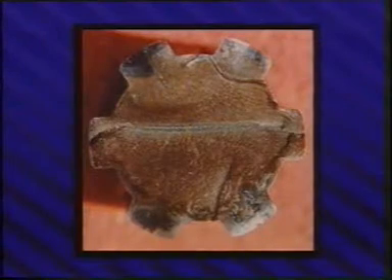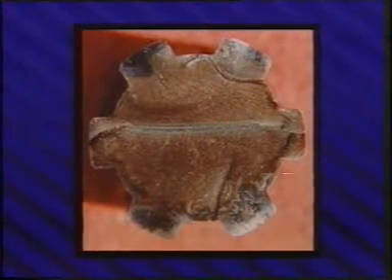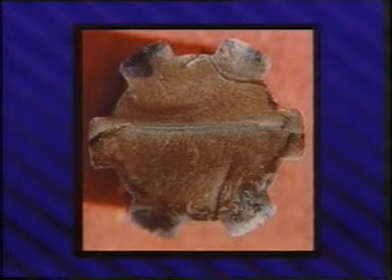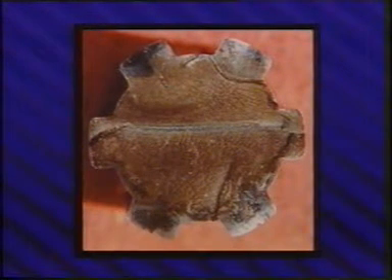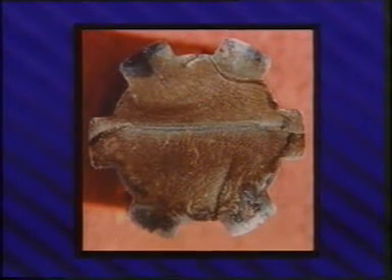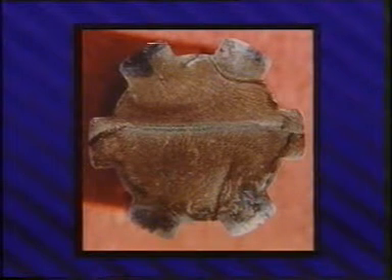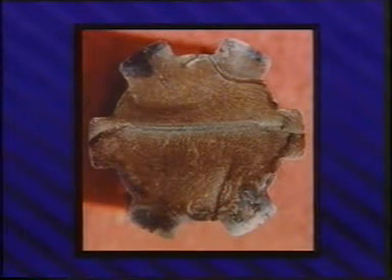These points are determined by the shape of the part or by surface and metallurgical imperfections, such as scratches, burrs, or other fabrication flaws. Foreign materials and hard particles in the metal can also determine the site of crack initiation. A great number of fatigue failures in otherwise lightly loaded structures originate in fretted or rubbed areas. In any jointed structure with some relative motion at an interface, fretting provides a possible location point for the initiation